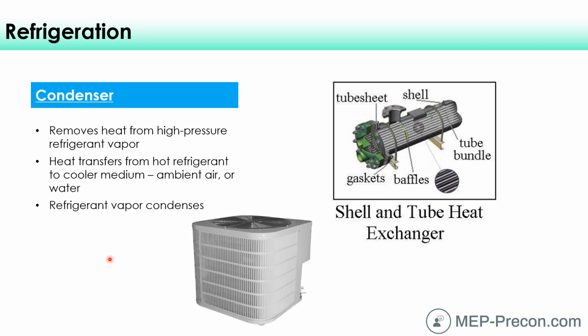So it might have a cooling load requirement in there 24 hours a day, 7 days a week, which is separate from the rest of the building, where you could shut down the main HVAC system on unoccupied hours, or at least go back into some setback conditions so that you're not spending so much energy to keep the building cool from a tenant standpoint, because it's unoccupied, there's no tenants in there. But the IT room or electrical closet, no, that's going to have a constant load. It needs to have heat removed from it all the time.